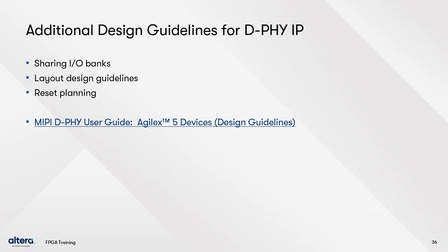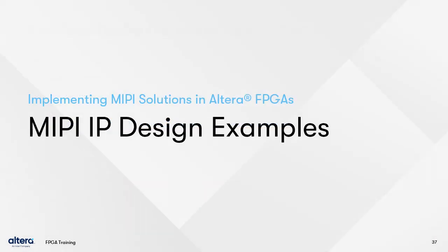The MIPI D-PHY user guide contains additional design guidelines and recommendations. It includes information on how to share I/O banks with the MIPI IP, recommendations on board layout, and planning a reset strategy. For our last section, we will take a look at the MIPI design examples.